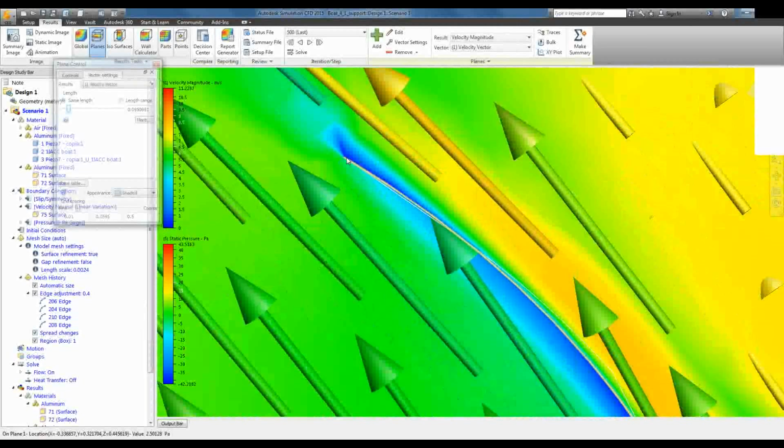Of course, with the America's Cup, it's too small to see a little tuft of yarn that might be wrapping around the back of your sail. But if you start to see, say, your telltales wrapping around to the back of the sail, you know you've done something with your leech to make the sail too tight. You don't have the clean flow leaving from the sail, and you're inducing drag, or that's slowing you down.